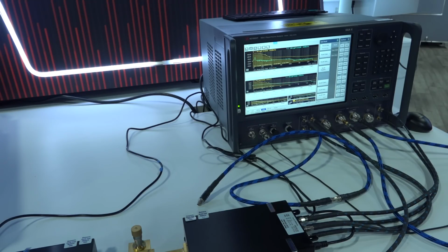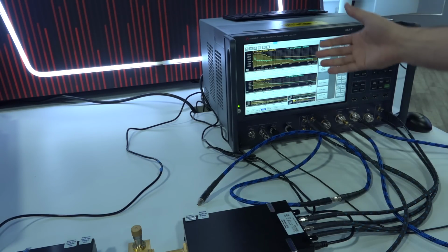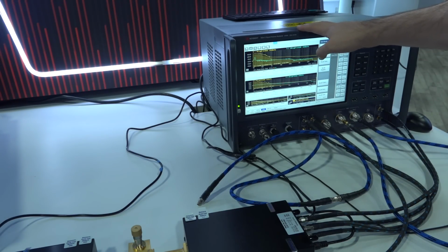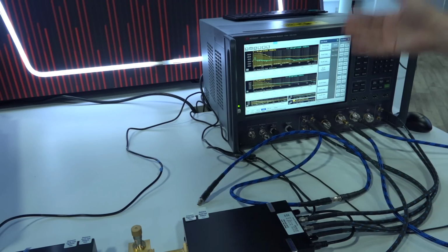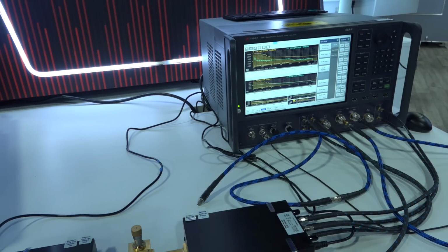And here we have the SSAX signal source analyzer. The 54 gigahertz version of this was finally announced in January. This is an interesting instrument because it has multiple different capabilities in one. It can do network analyzer, phase noise analyzer, VCO analyzer, and of course it has cross correlation capability. And because of that, there are a lot of unusual setups you can put together and measure a lot of things at the same time.